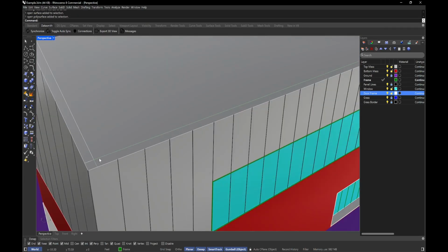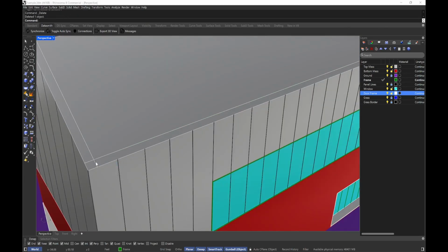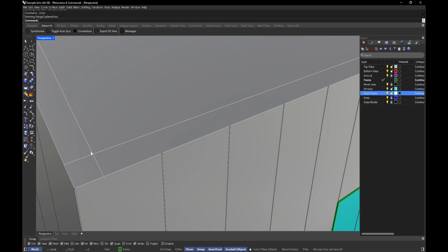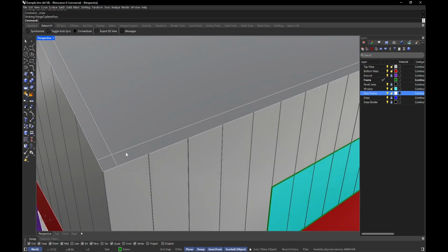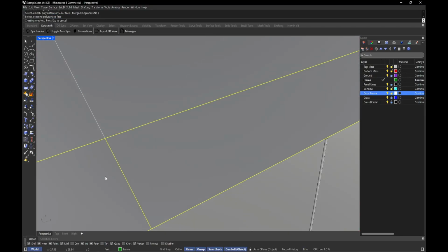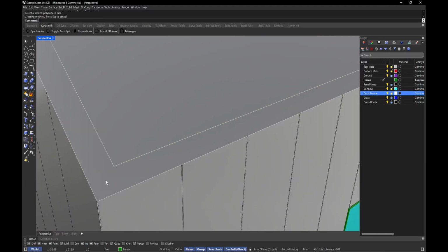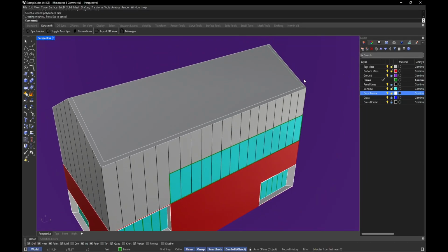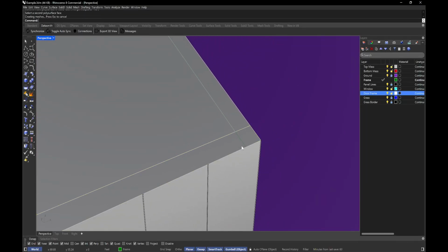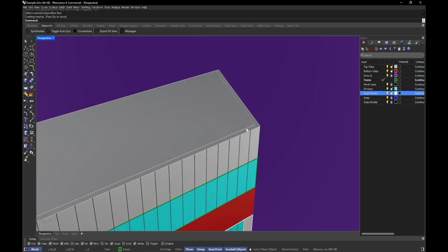And you see, if you want to get rid of these, let me get rid of this. These division lines can be annoying sometimes if they're already coplanar. You can also just reduce the geometric lines of your modeling if you do merge coplanar face, right? I can merge this and this. You see how that becomes one? Merge that and that. So this becomes this nice clean geometry, right? Like that. You see?